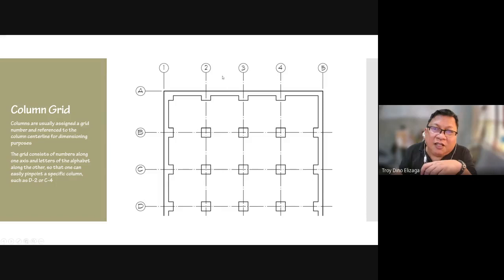And if it is something that was added after you already wrote your 1 to 5 here, what some architects normally do is they put 2 prime, or 2a, small letter a, and then here's a prime or a1, a small one or something, if there's more than one. So what's important is that all columns are accounted for.